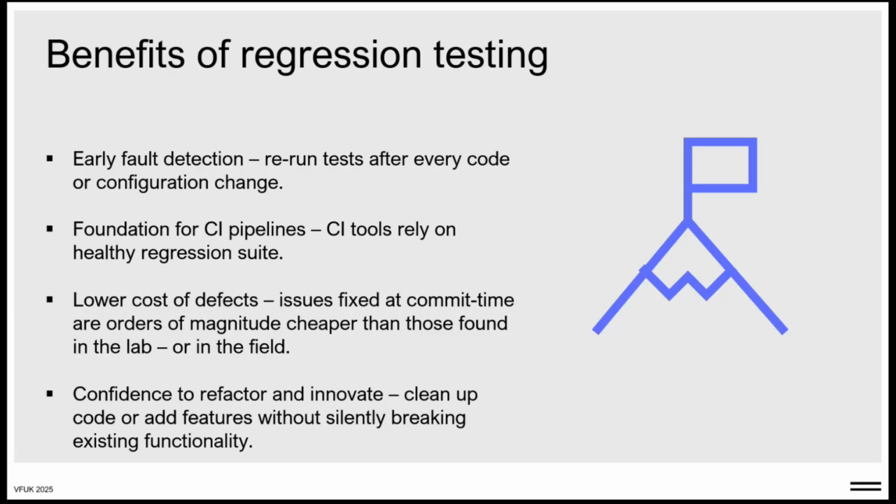So now that we know what regression testing is, why do we need it? Regression testing gives us confidence. Every run proves that the design still behaves as before. We also get early fault detection. The tests run right after each change, so we catch new bugs the same day and not weeks later when we have forgotten what we did.